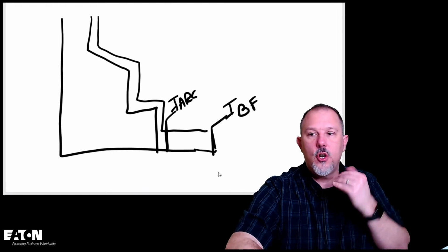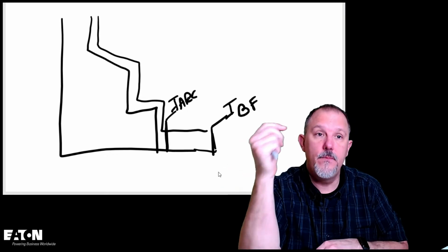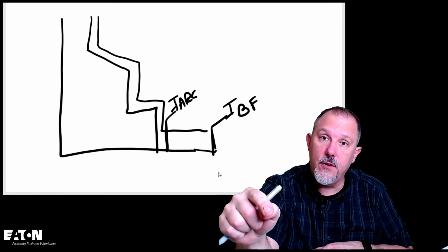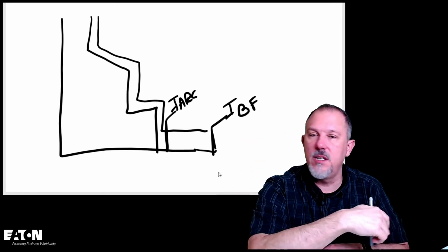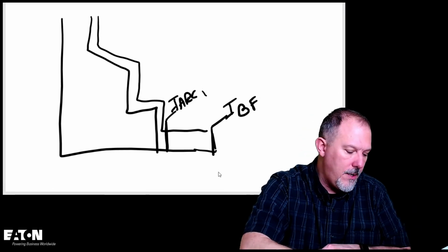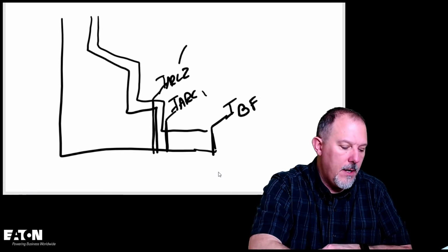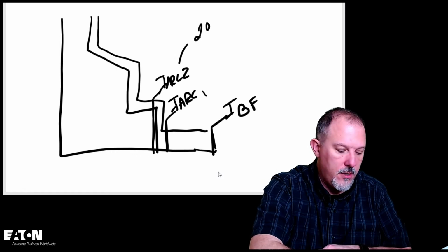It gives me an equation to calculate arcing currents, and I calculate two values. In the 2002 version, you calculated one value and then you simply took 80% of that value to get IARC1 and then IARC2. In the 2002 version, this was 80% of IARC1.